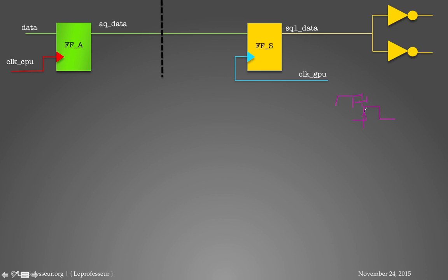So this is the rising edge, and the data signal should be stable. This is the setup window. And the signal also should be stable after the rising edge of the clock for a certain time, which depends upon the technology requirement, and we call it hold time. Separately, these are called the setup window and hold window.